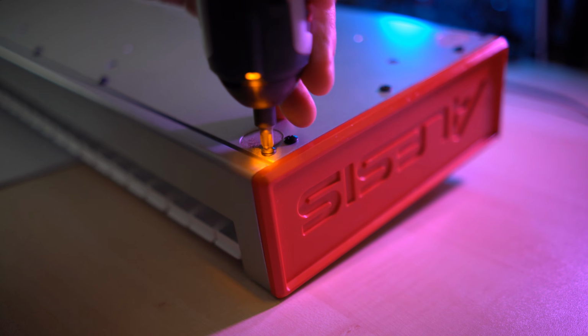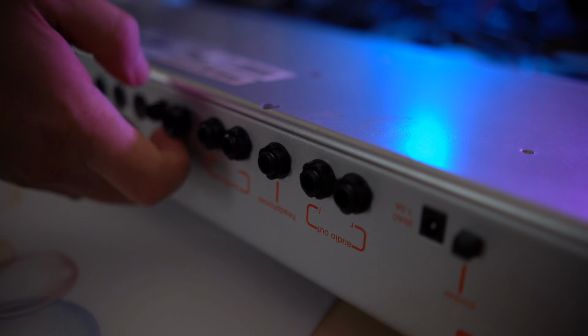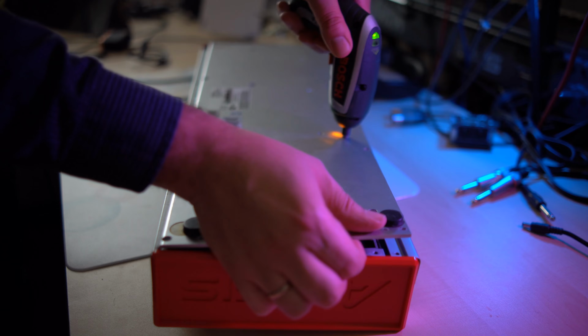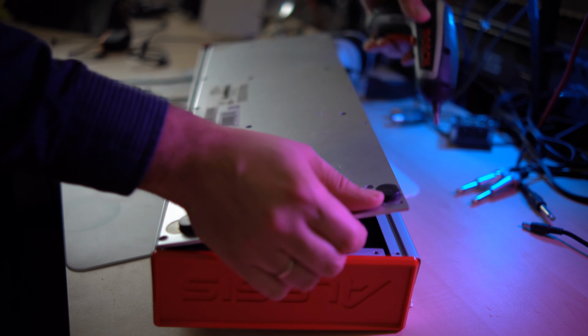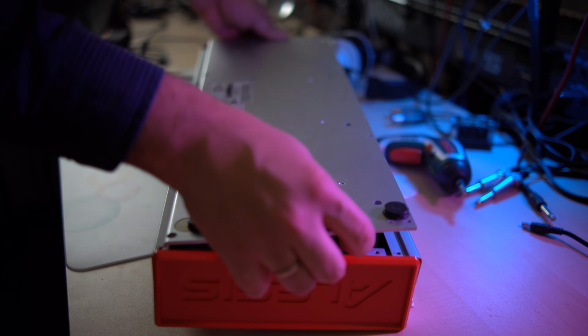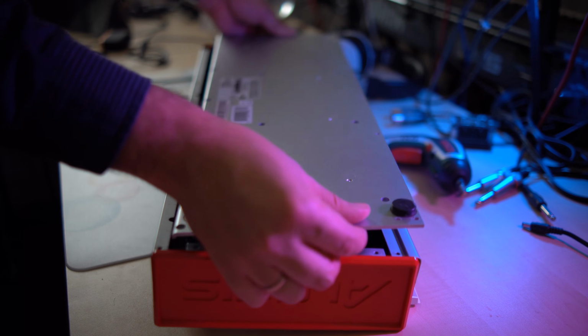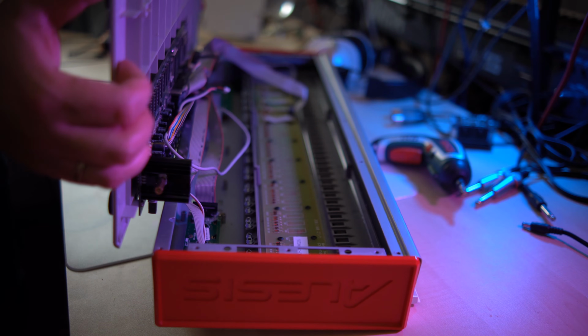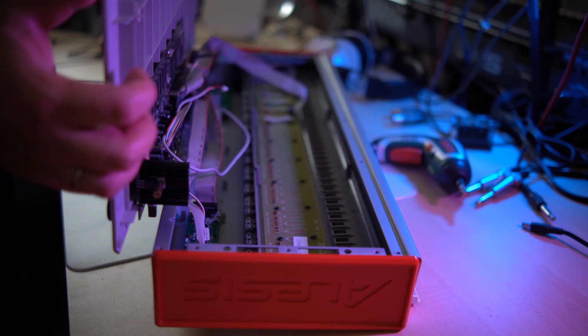Just remove all the screws holding the bottom plate in place and then unscrew the audio circuits on the back of the synth. You should now be able to carefully lift up the bottom plate, revealing the keyboard and an assortment of 4 circuit boards. The Micron has a very clean layout, so it's relatively easy to reassemble it.